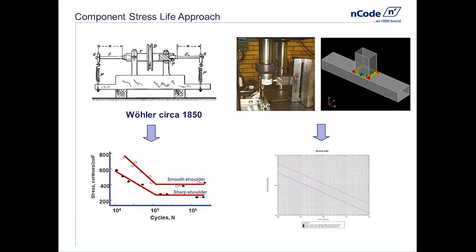Residual stresses, stress risers such as the shoulder fillet in his axle, anything in terms of surface finish effects, all are embedded inside that SN curve. We're going to do exactly the same thing for our weld curves.